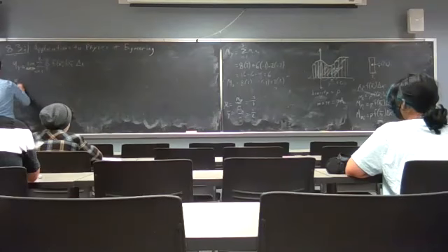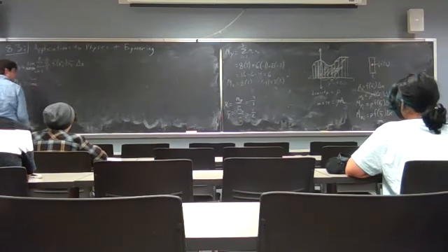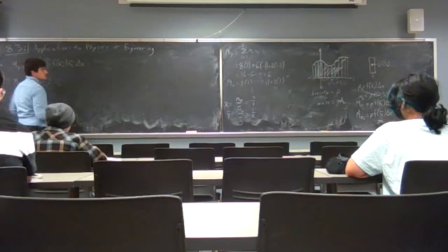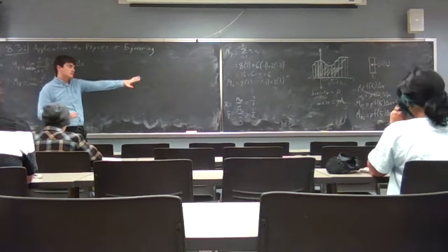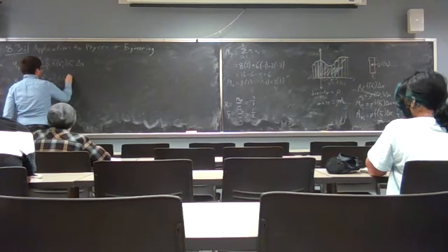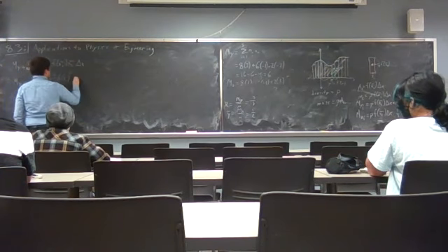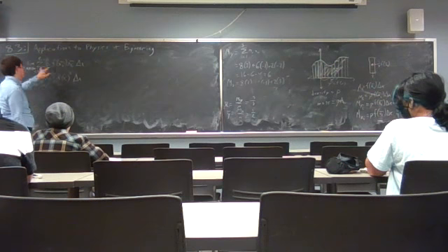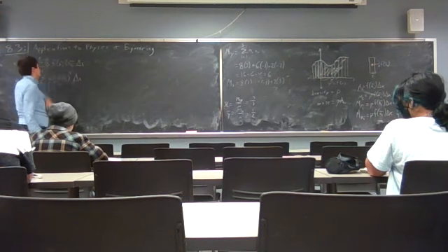And for M_x, the limit as n approaches infinity of the sum from i equals 1 to n of rho times, now I want to take the f of xi bars there and just multiply them together. So I get 1/2 f of xi bar squared times delta x. Okay, but this is an integral, right? Or with the limit, this is a Riemann sum because we have our function and we have the delta x.